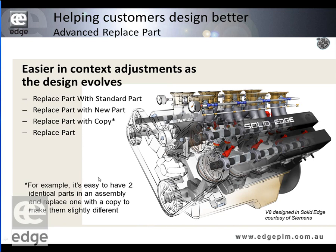And we've reworked the replace part command entirely. So you can replace a part now with a standard part. You can replace it with a new part. You can replace part with copy. We'll look at that in a moment. And of course the old replace part command.